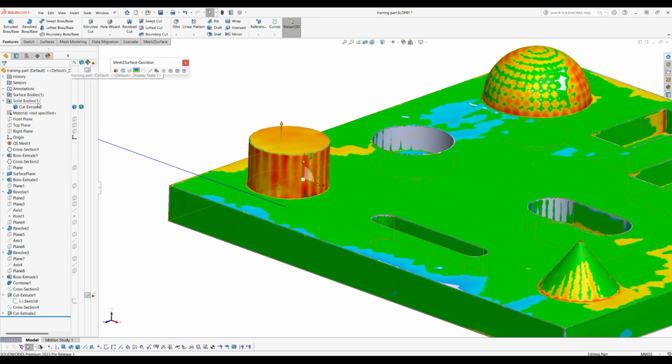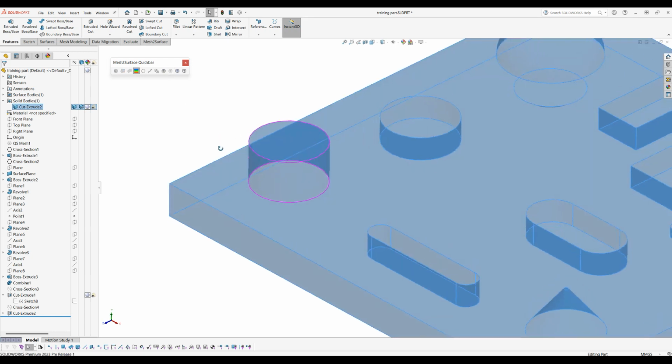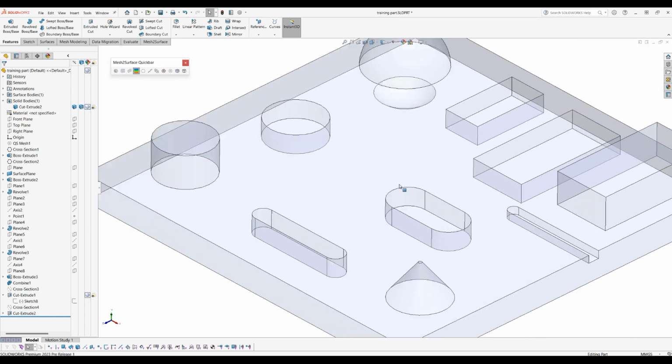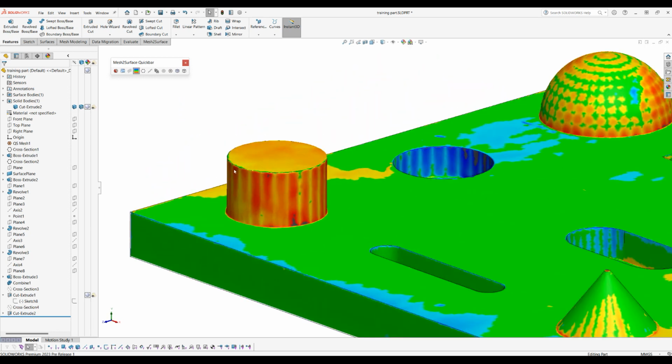I will show my mesh, and what I'm going to do now is expand this feature tree, and for my solid body I'll select the option to render it transparent. Let me show you the result. This means that the object looks something like this. The main idea is that because the object is drawn transparent, now you can easily see the underlying mesh. I will just show the mesh so you can see it on the screen.